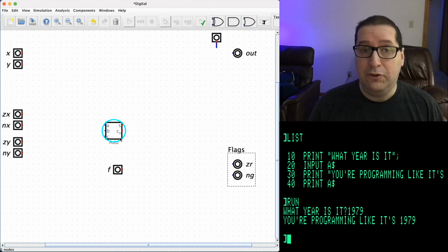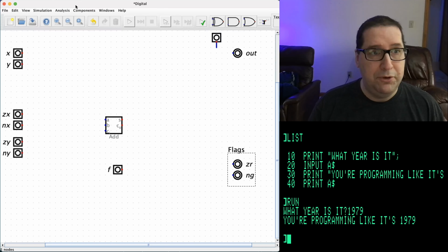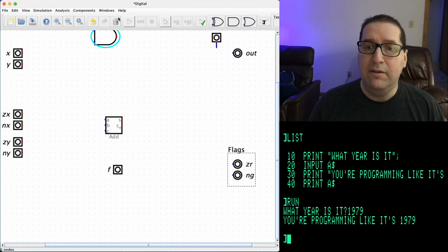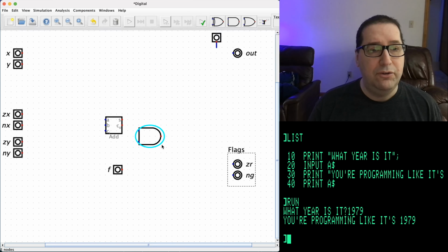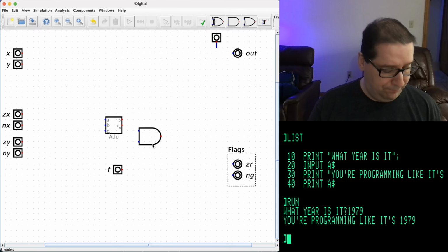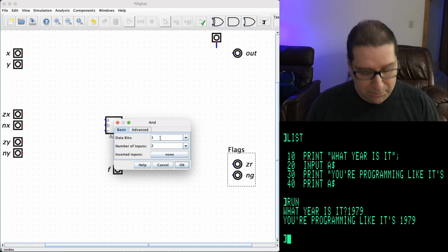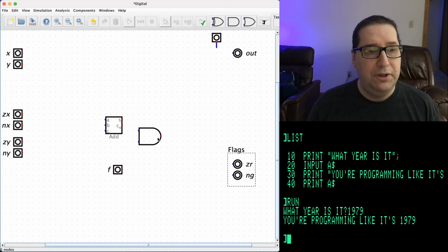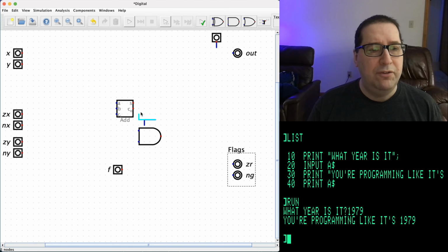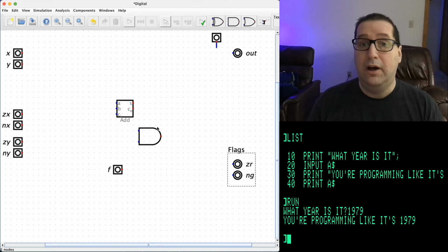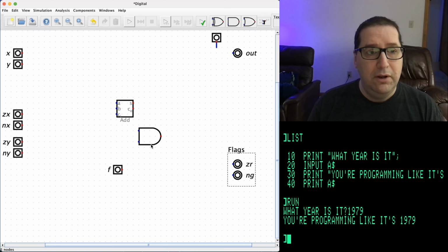That's going to be our X plus Y as one possible component. And second, we might have a 16-bit AND. That's our other component. So that needs to be a 16-bit AND with two inputs. So whenever we're thinking about selection or choice in the context of a combinatoric circuit, we know that we're thinking of either a mux or a demux, right?